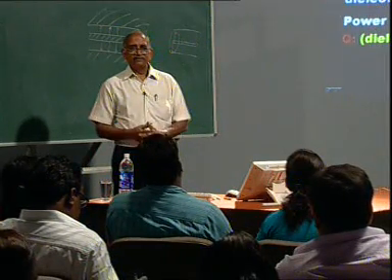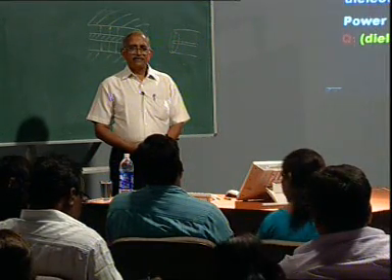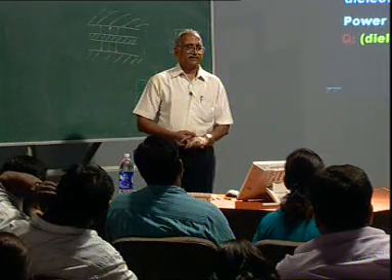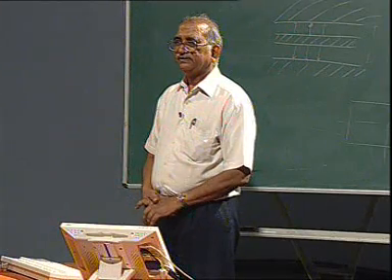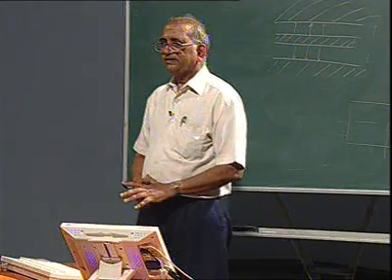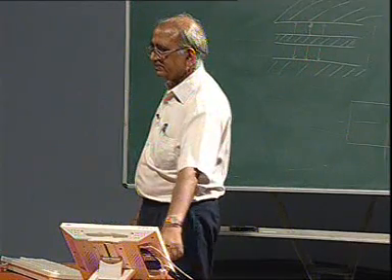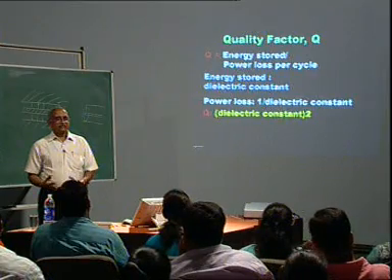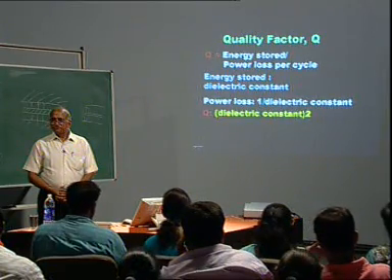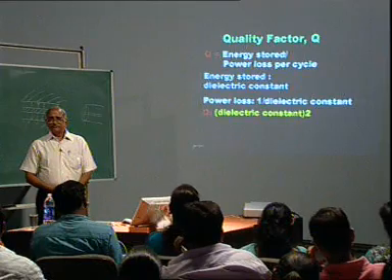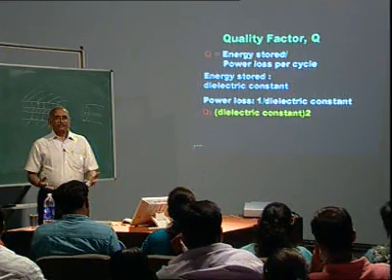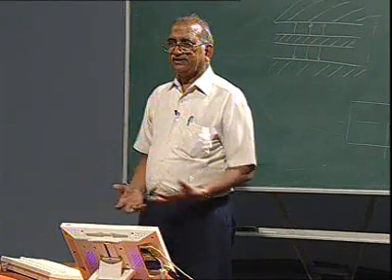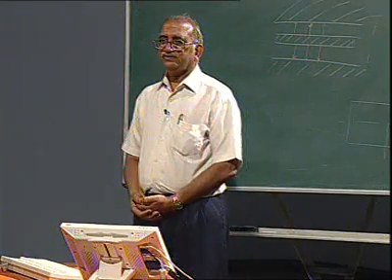Although we are talking about a resonator, the antenna we are using is a resonator, but not a perfect resonator, it is a lossy resonator, because it radiates power. And the Q of this lossy resonator is proportional to the dielectric constant. So, if you increase the dielectric constant by a factor of 2, Q will increase by a factor of 4, and when Q is more, what happens to the bandwidth? Bandwidth is going to decrease, because how do you define Q?